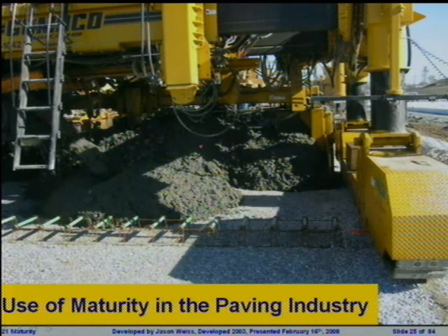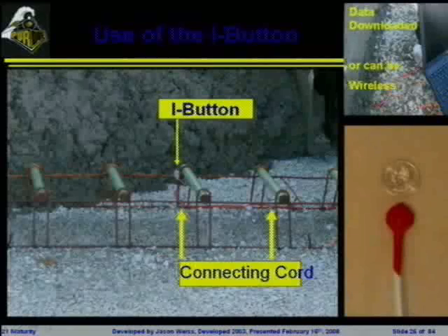So I mentioned the paving industry is going to be using this enormously. You can't see it, and I can't even find it right here. The only way I even know that it's here is you can see here we've got a bright orange spot. The bright orange spot meant don't rip up the thermocouple wire that's underneath the paver, and there'll be a thermocouple attached, and I believe it was attached, I'll draw it right there. It was attached on one of the dowel bars so that we get the temperature in the middle of the pavement as it goes down.